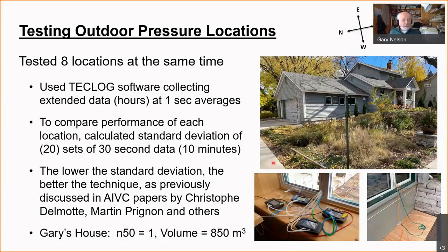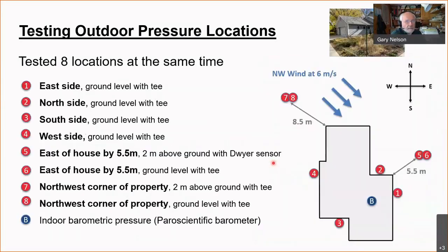So I'm then going to calculate the standard deviation of those 20 30-second averages, and that will be the measure of how good or how stable the pressure is during this 10-minute period of time.